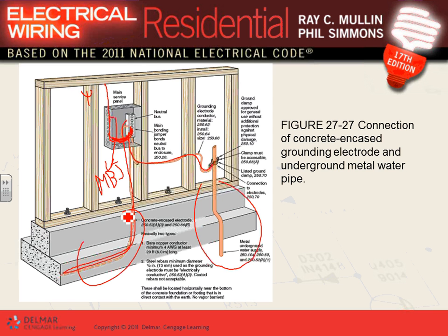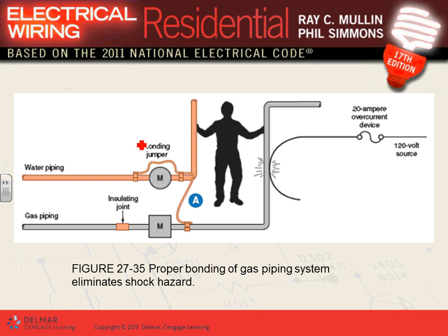That's how we ground the neutral and the equipment. Can you guys see that also the equipment here is bonded? The box itself is grounded. So right at the service, we ground the neutral and we ground the what? The equipment, the box. Ground the neutral and we ground the equipment, the box.